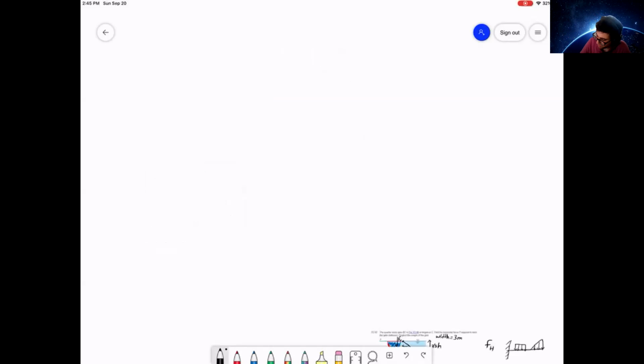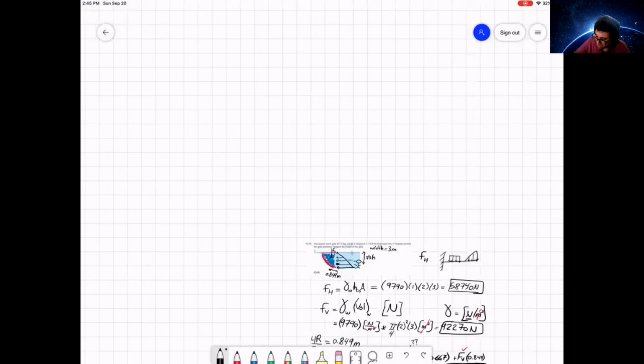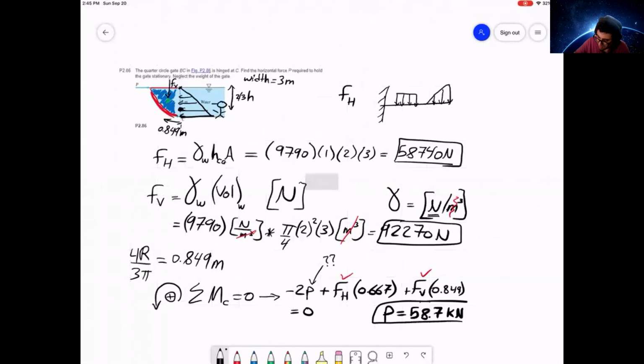If you write just H for this one, you'll use 2 instead of 1. So that's why we write HCG. That way we know it's the centroid, so we have to use 1 meter. Otherwise, if you use 2, your entire calculation will be wrong. That's how I like to label stuff.